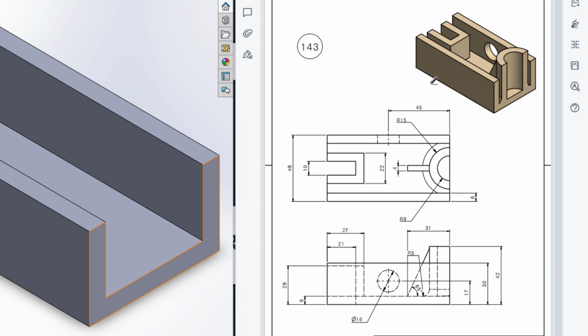So this time I will draw this shape. For drawing this shape, I will first draw a center line here, and this center line has a dimension of 21 unit. So after drawing this center line, then I will offset this portion. So after offsetting this portion, I will offset again this portion. Then I will close the shape. Then I will extrude boss it to 28 minus 6 unit. Okay, so let's do it.